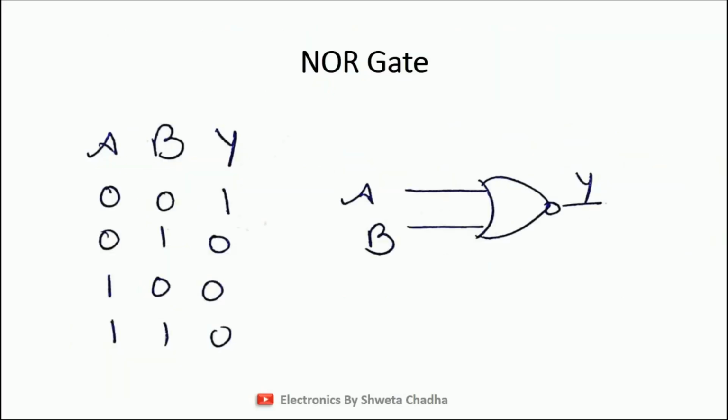The second type of latch which I'm going to discuss is with the help of NOR gate. But before starting that, let us discuss a NOR gate table. So this is your NOR gate. NOR gate is a combination of OR gate with NOT gate, as you can see over here in front of an OR gate. So I have taken again 2 inputs, A, B, and I have written all the 4 possible combinations that we can have: 0, 0, 0, 1, 1, 0 and 1, 1.